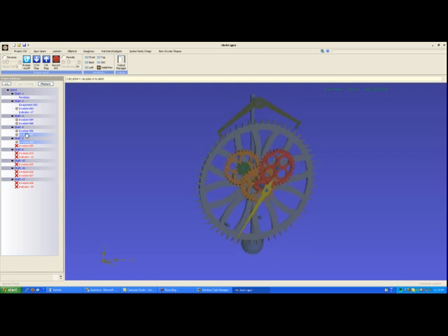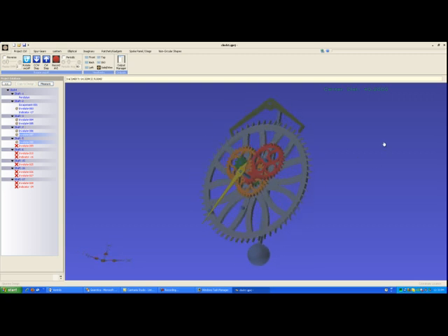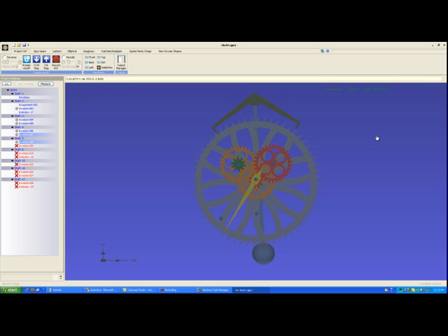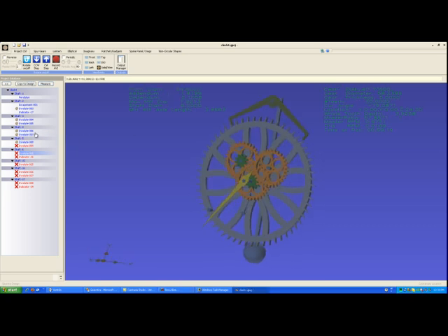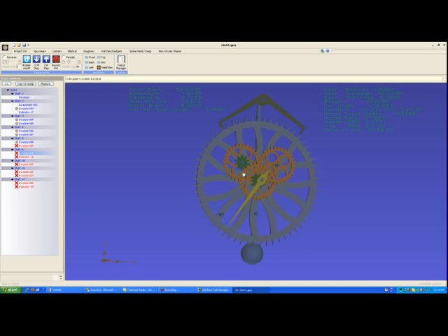So I want 2 gears with a ratio of about 2.3 to 1, and I want them to end up on the center shaft so I get an hour hand. Well, it turns out that a good number for that is 14 and 30. If you take 30 and divide by 14, you'll come up with a number which will give you almost exactly the ratio we want.